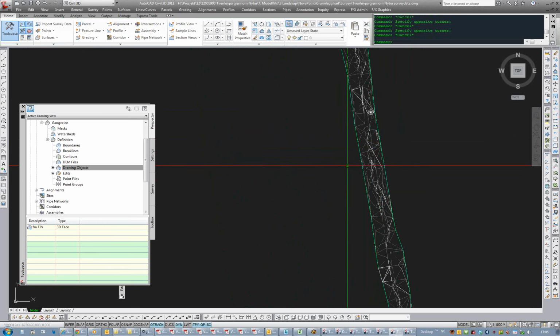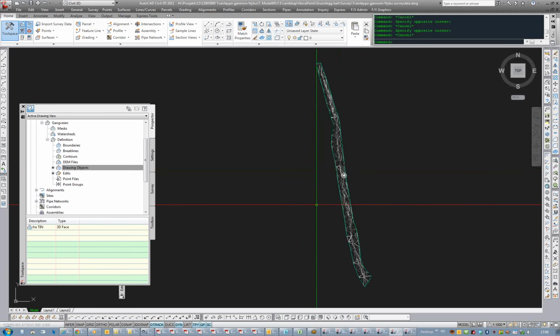You create a data shortcut. Oh yeah. Now, just so I get my head around the philosophy here, am I doing all these data shortcuts like I would an XREF? I go to my base, my main drawing, and then XREF everything into it? Yes.